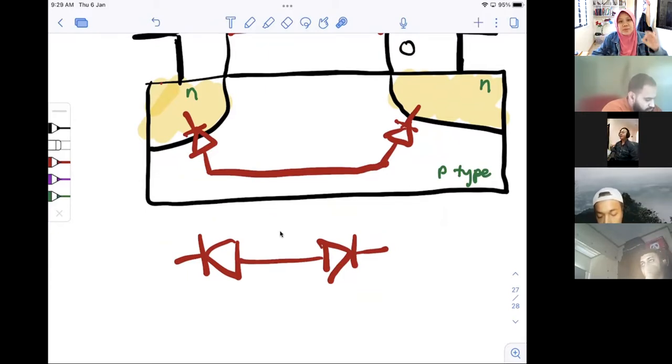Reverse bias is supposed to give 0 current, right? You shouldn't have any current in reverse bias of a diode. But when we draw the I-V, the current voltage, you will see that in reverse there's a very small current, maybe picoampere, 10 to the power of minus 12 amp. So even in the ideal case there is still current.